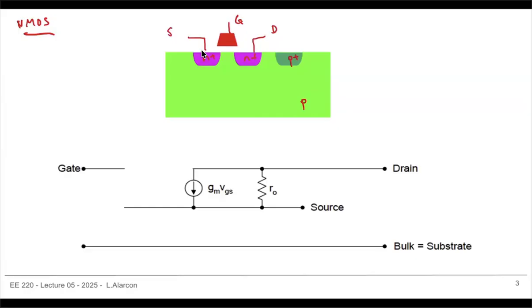But remember the reason why, if you connect this to the body, hopefully everyone remembers, the reason why we have a P plus is to prevent the formation of Schottky diodes. So just to make sure, remember we had our Schottky diodes. Schottky diodes are metal semiconductor contacts.